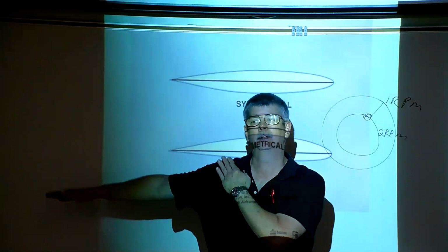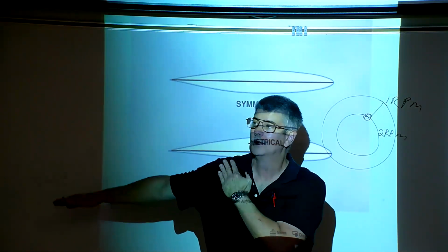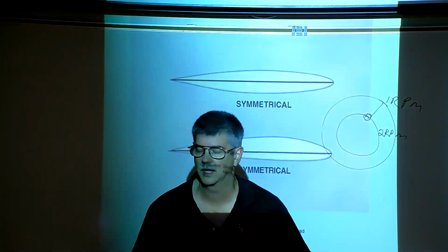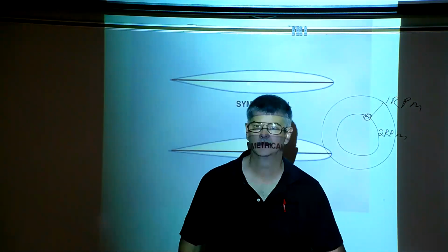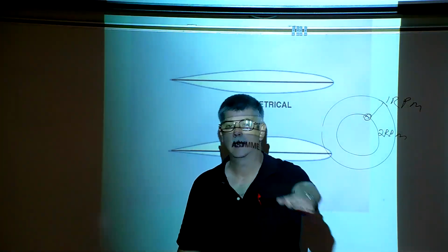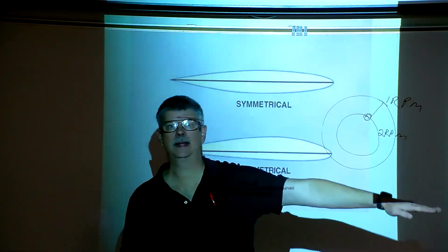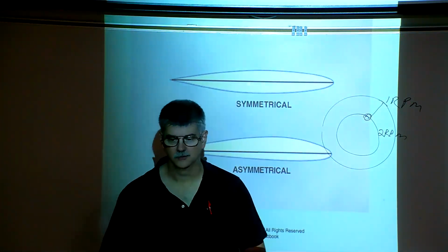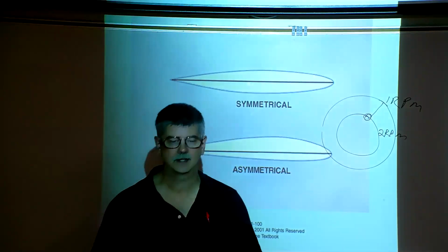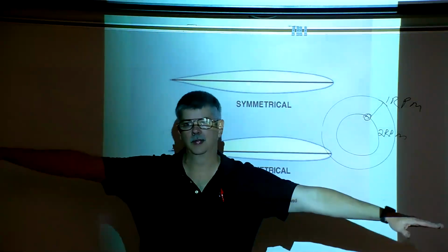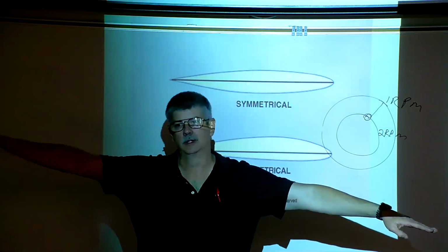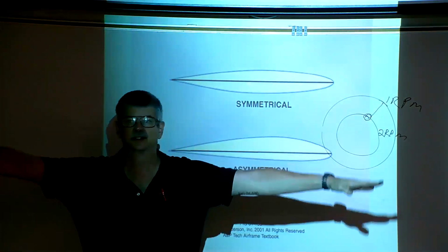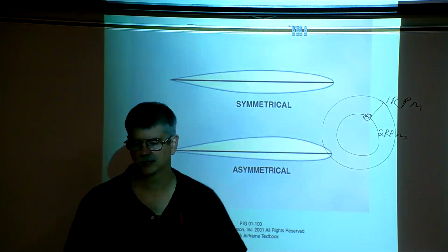So keep in mind, questions for tomorrow. The blade that flaps up, does the angle of attack increase or decrease? And the answer is the angle of attack decreases. Now, on the other hand, the blade that is flapping down has decreased the vertical velocity, and thus the angle of attack increases. By the advancing blade reducing its lift, and this one increasing its lift, it now balances out.